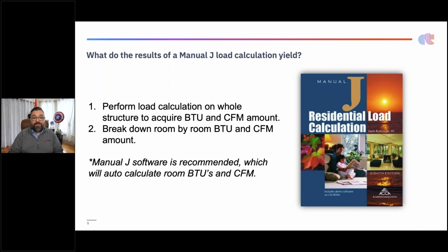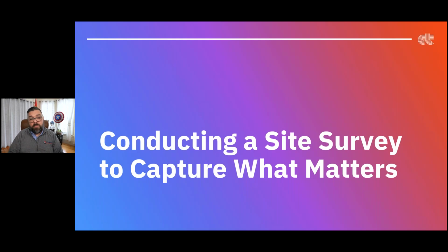And in order to do this math correctly, you've got to use software. You might be able to do heat loss with an Excel document and end up with the same number because it really is that simple. Temperature difference, surface area, U value of the wall or the door. That's easy. The problems really come into the heat gain side, and that's the cooling side, and that's how we actually select heat pumps. So with a focus on that, with carbon reduction across the country and rebates going up and all of these opportunities, we have to make sure we get this right in order for it to work for the homeowner. And that's really about providing comfort, right?